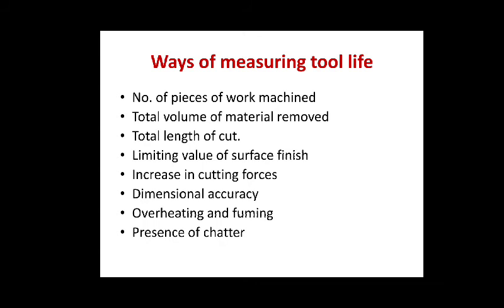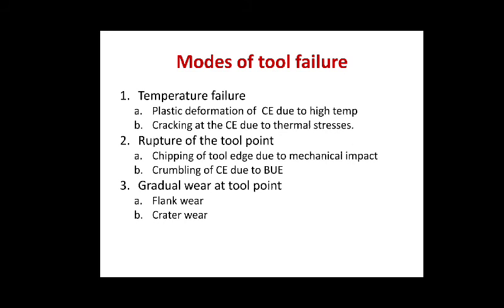Now let us see the modes of tool failure. First, temperature failure: plastic deformation due to high temperature, cracking due to the thermal stresses, rupture of the tool point, chipping of the tool edge, crumbling, gradual wear at tool point, flank and crater wear.